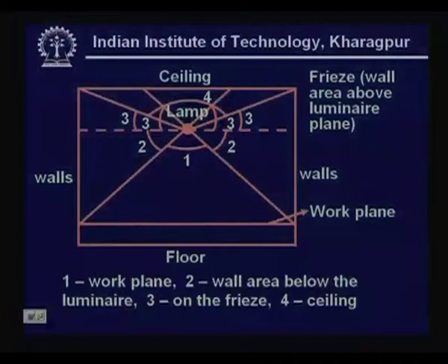So there it was necessary to suspend the lamps, whereas modern buildings where the ceiling heights are lower these days, especially for interior work where a controlled environment is necessary, keeping in mind the load it may pose on the air conditioning plant, are always provided with a false ceiling and the lamps are placed recessed in the ceiling.